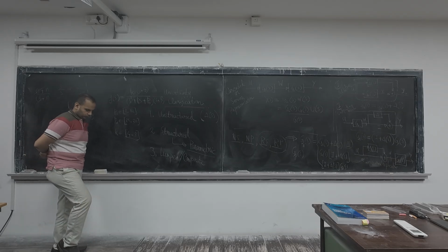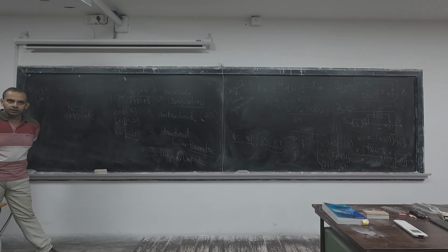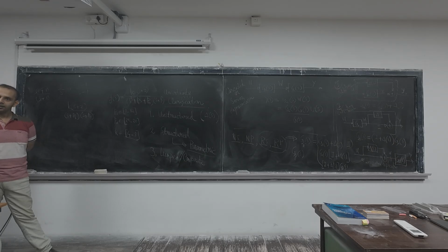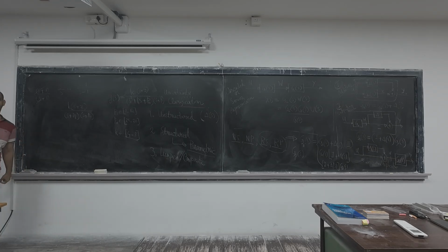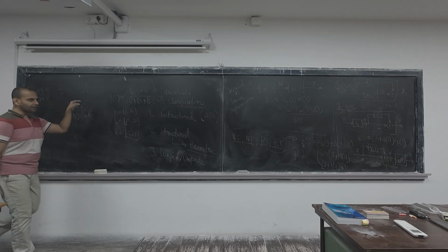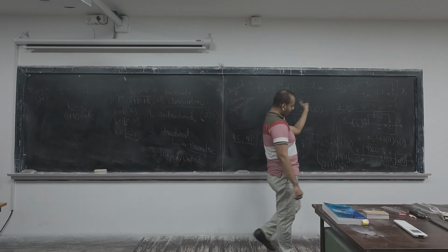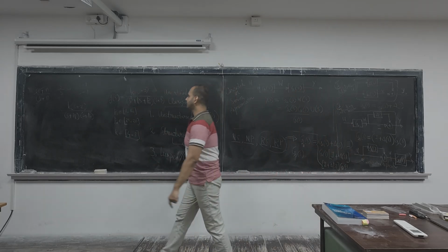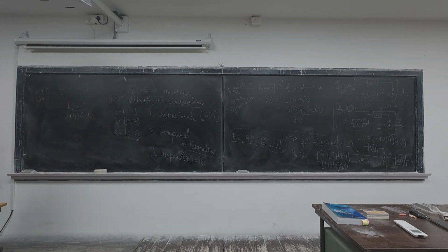Once again, a stable pole zero cancellation, that means pole zero cancellation on the open left half, although undesired, does not create any stability problem, right? I hope you have understood. Whereas a pole zero cancellation on the imaginary axis or on the open right half may even lead to an instability problem. We will learn that in detail when I start internal stability. Then we will see why an unstable pole zero cancellation is very dangerous for us.